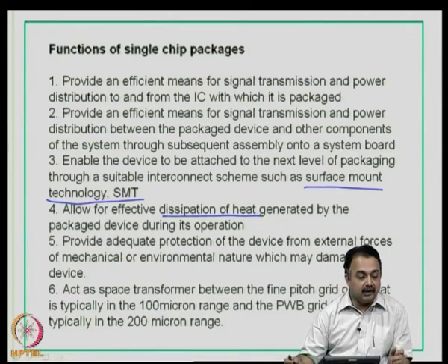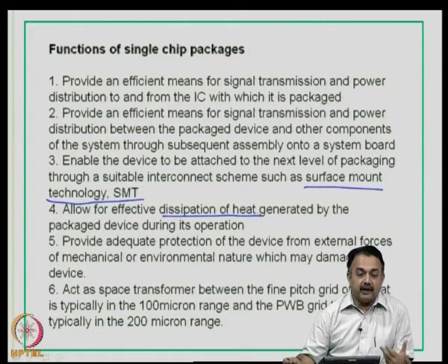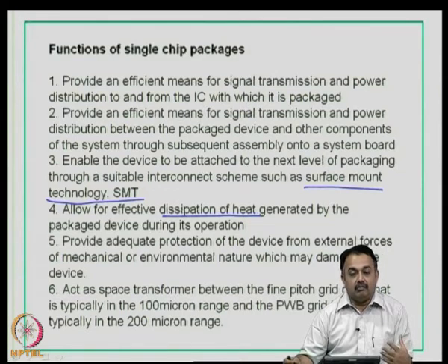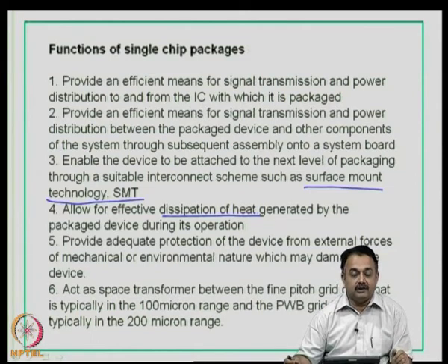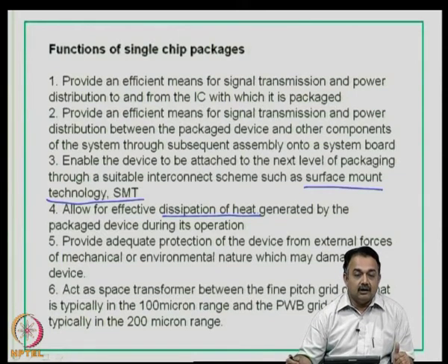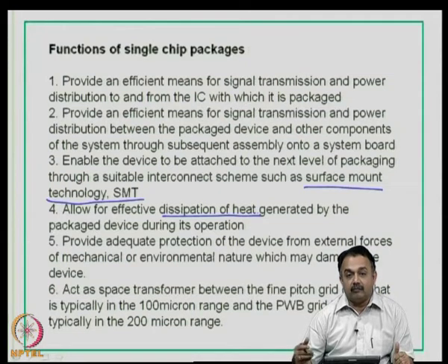So, obviously, when you look at any package, depending upon the size, the package volume also increases. The package volume and the package material, therefore, will have to take care of temperature changes, moisture changes in the particular area of operation of the device, and then dust, and then finally other electrical or other mechanical interruptions like vibration or a shock and so on.